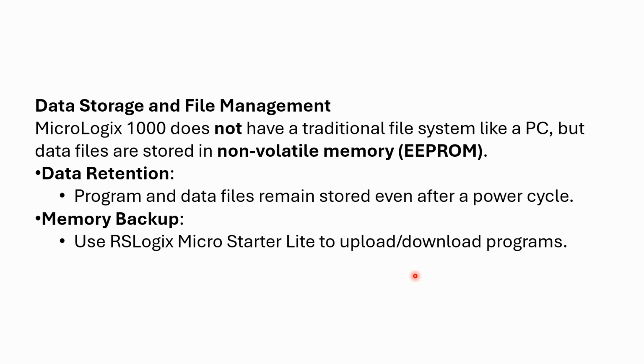But for memory backup, you want to use RSLogix Micro Starter Lite. It allows you to upload and download programs, so there's really no excuse to not have a saved copy of the program if you have the software. You always want to make sure you've got a copy of the most recent files available.